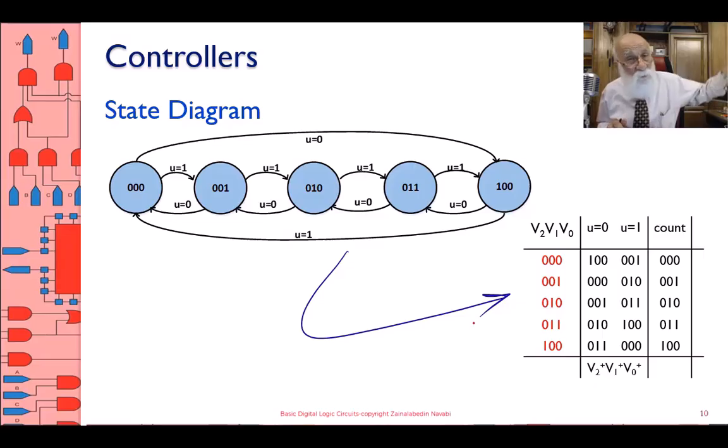So unlike what I showed you at the end of the flip-flops, where the state table is what we started with, what I'm saying is, yeah, for easy ones, you can do that. For more difficult ones, where more decisions are being made, a state table or transition table is not what you can start with immediately. You better start with a state diagram and then eventually from there go to the circuit, which will show you the steps.